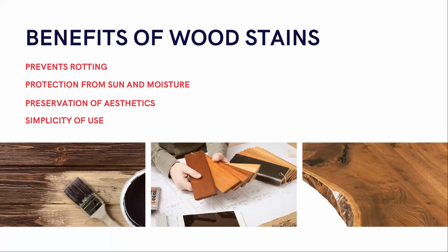be aesthetically pleasing. And then simplicity of use. So there's no doubt that stain is easier to apply and to maintain because stains can often be used without a primer, potentially halving the time of required application. While the need for maintenance does vary with the climate and product, even heavily trodden wood steps are likely to need restaining only once every 3 years.